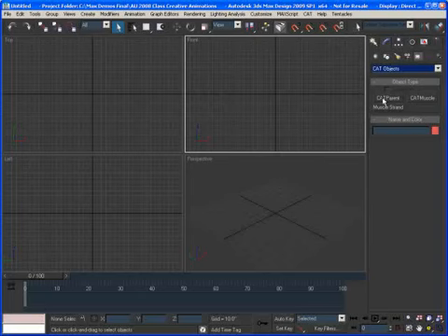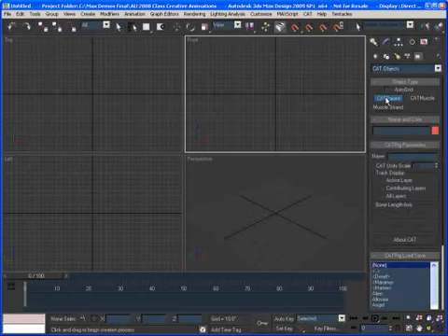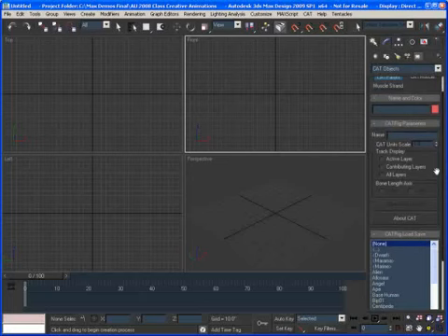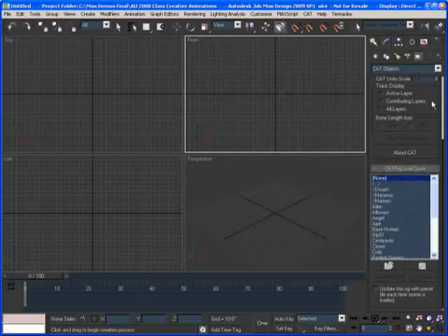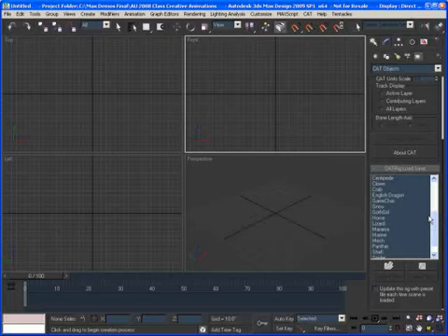But first of all, we're going to talk about the CAT Parent, which is the core of the CAT animation system. So when you click on CAT Parent, you'll see that we've got a couple of options there. But basically, when you create a CAT Parent, you're creating the basic, I would not call that the root node, because it's not exactly a root node, but it's the parent of the whole character, the character set if you want, and you can create any type of rig that you've got here. And all of the rigs that are listed here, except for the dwarf one that I created myself as a test, are available with CAT for free when you install it for the first time.